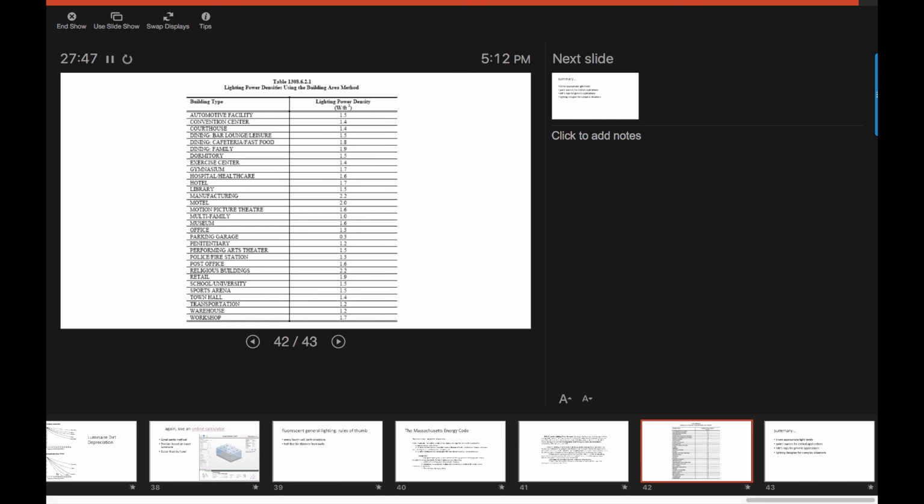Now, there are more subtleties to it, and if you're finding that you're very close, and it's an important project, you would obviously want to call an electrical engineer or a lighting designer to do a more detailed calculation. But for our purposes, you can do this by basically using your light fixture schedule in Revit, and it will add it up for you. It'll multiply through the number of fixtures occurring in your project, and it'll give you a pretty good ballpark.